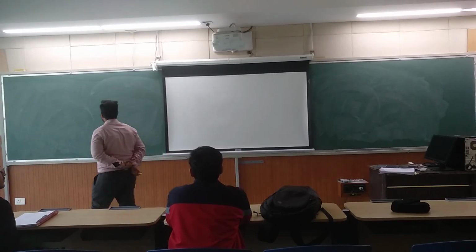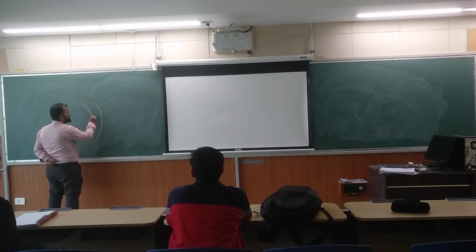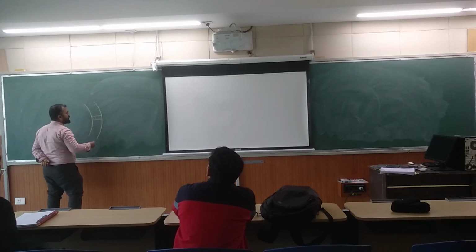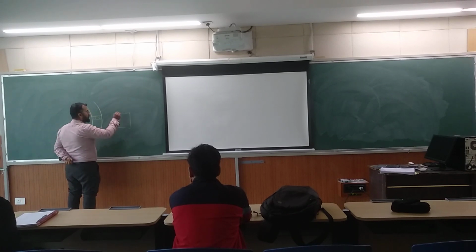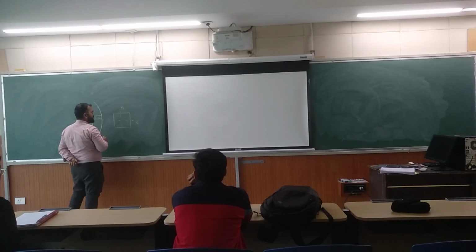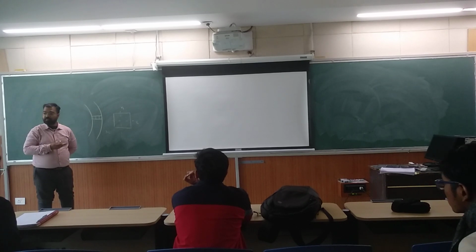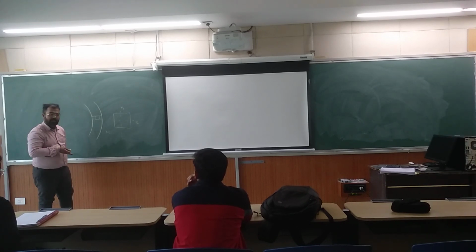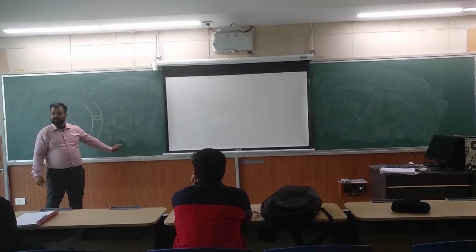How do we get the nodal values? So we took one structure and then we made some elements here. Then we take one element out and then we define our epsilon and eta. Then we find out the Ni's. What are Ni's? Ni's are functions of epsilon and eta, right? From that we describe u as a variable, Ni, ui, and then all the story goes on from here.